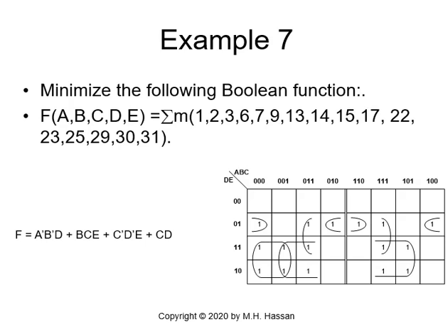If you look at the example, we have the sum of many minterms, and we would like to group them as follows. After we put all the minterms based on the minterm location, we follow up with those. We will have those 2 as a group of 2. The 2 ones here with the 2 ones here are logically adjacent and will be a group of 4.